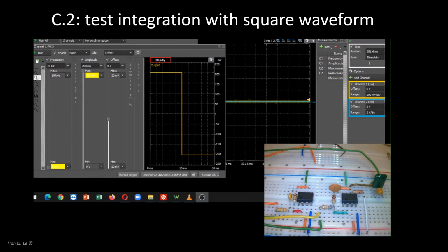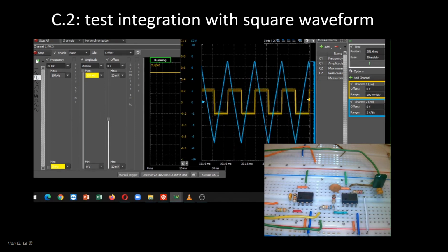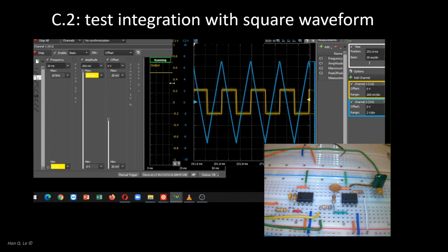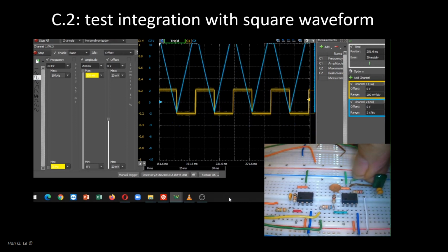A symmetric square wave was generated, shown as the yellow scope trace. The integrator output is represented by the scope blue trace. The non-vanishing DC component could be roughly estimated by comparing the AC coupled output versus the direct output by moving the scope green wire back and forth as shown in the lower right inset.